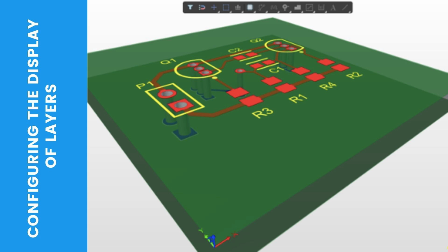We have electrical layers, which include 32 signal layers and 16 internal power plane layers. Then we also have component layers, layers used in the design of the components, including overlay, silkscreen, solder, and paste layers. Now, if an object is placed in a component footprint on one of these layers in the library editor, when the component is flipped from the top side to the bottom side of the board, all objects placed on a component layer are flipped to their partner component layer. This includes objects on user-defined component layer pairs.